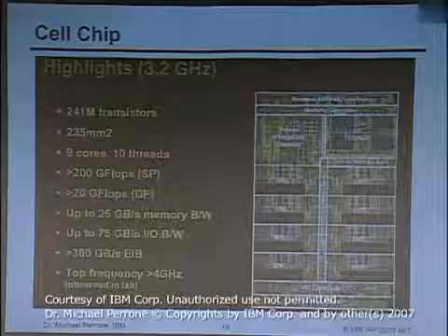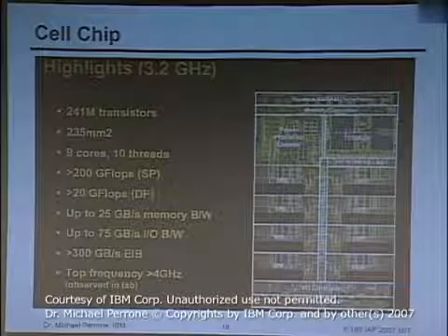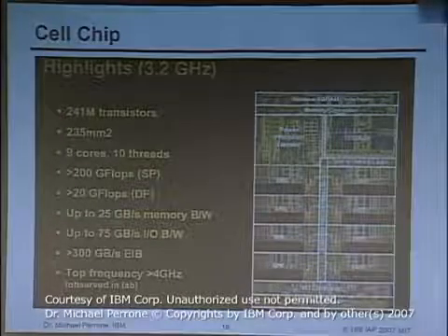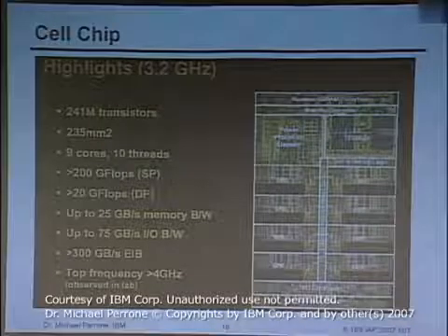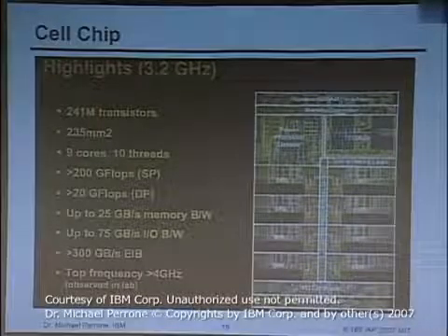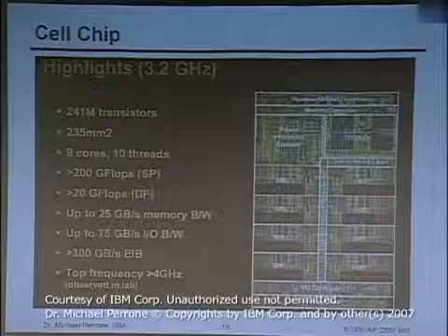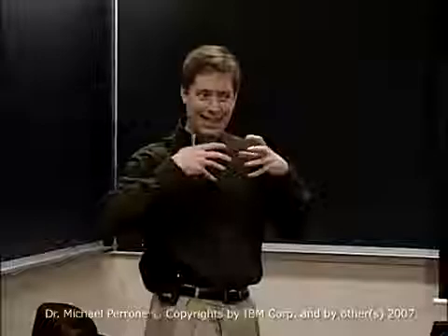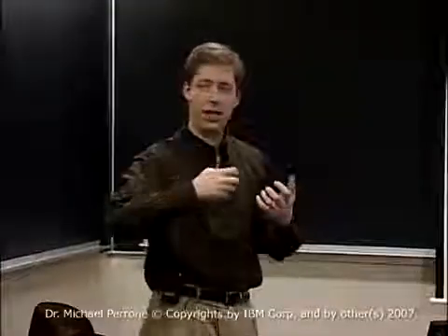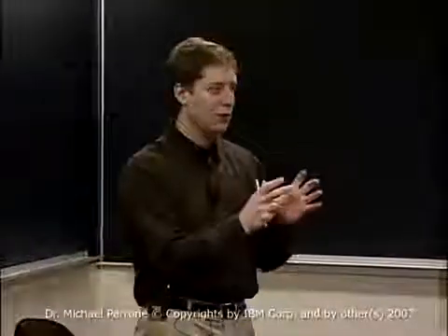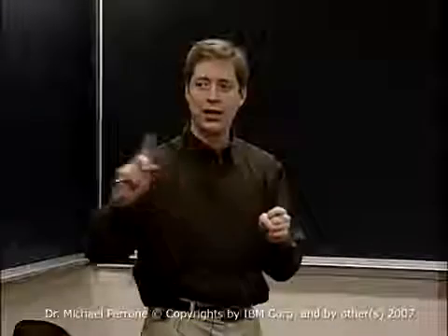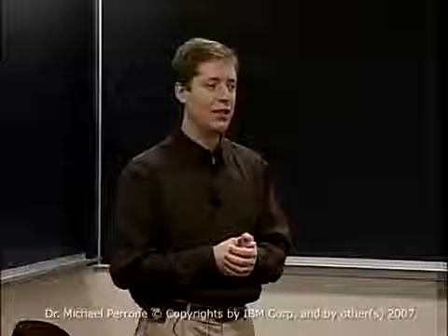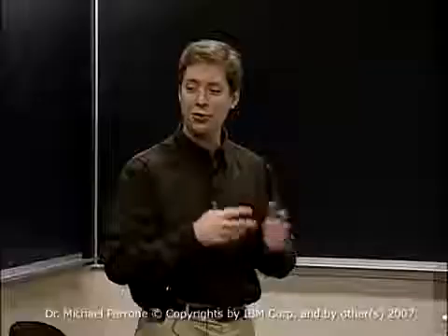Now, this chip really has tremendous bandwidth, but what we have seen so far, particularly with the Sony PlayStation, and I think you may have lots of them here, the board is not designed to really take advantage of that bandwidth. And even the blades that IBM sells really can't get that type of bandwidth off the blade. And so if you're keeping everything local on the blade or on the PlayStation 3, then you have lots of bandwidth internally. But off-blade or off-board, you really have to survive with something like a gigabyte, 2 gigabytes in the future.